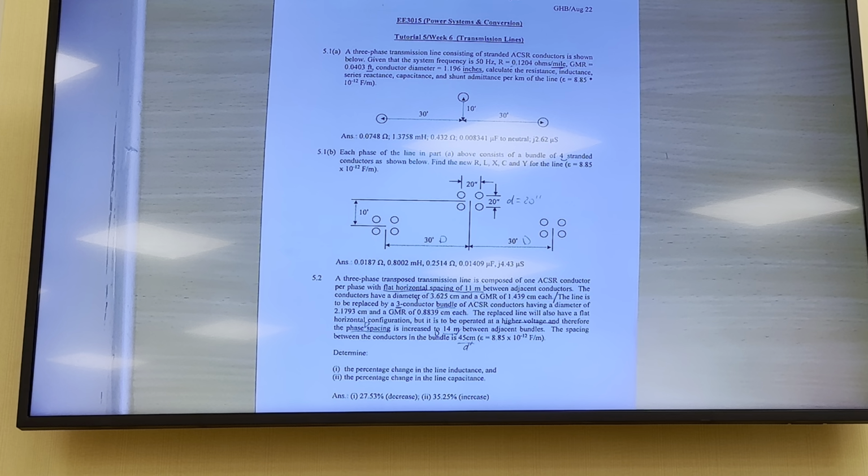What you need to do is to be careful with the unit of these formulas because essentially for the L and the C, what you are going to calculate is the inductance and the capacitance, which are respectively in Henry and Farad units. However, for power grid calculation, we need the value of impedance. So you have to convert the L and the C into the X. All right. So for L, the XL equals to what? 2 pi f times L.